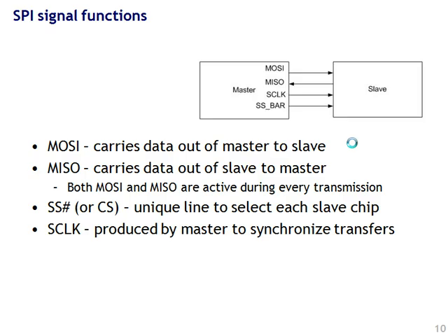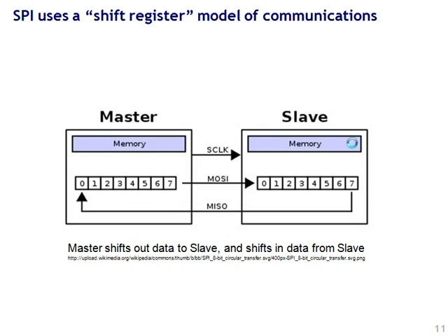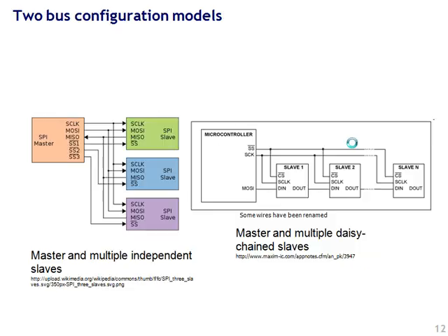Let's see now. I need a separate chip select or slave select for each slave. And internally, we're going to have to shift the bits out. Each time we shift out a bit, we'll have to cycle our shift clock so that the slave can get the clock and shift it into its shift register. And what do we got here? 3 separate slave selects with 3 separate slaves.